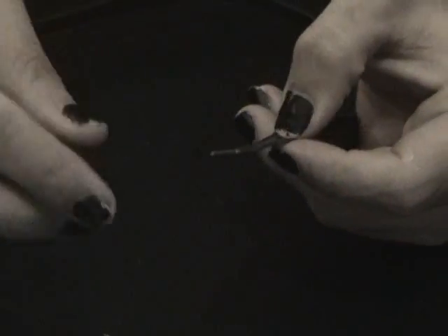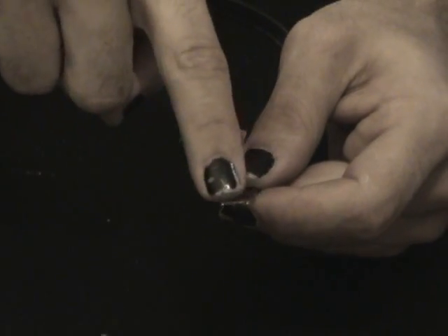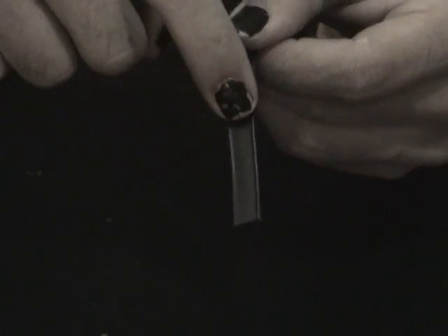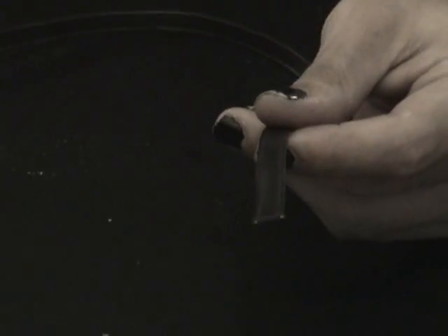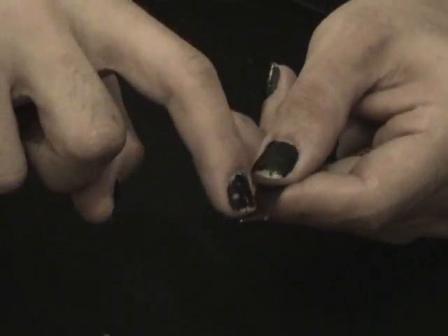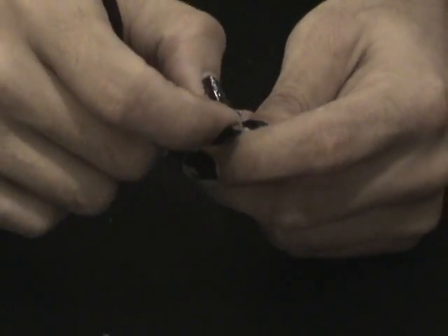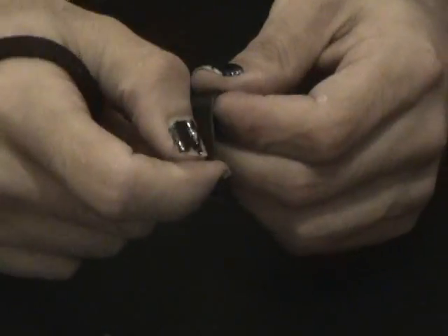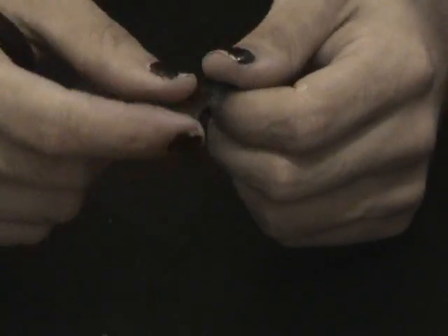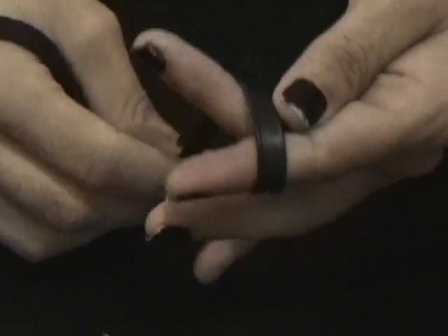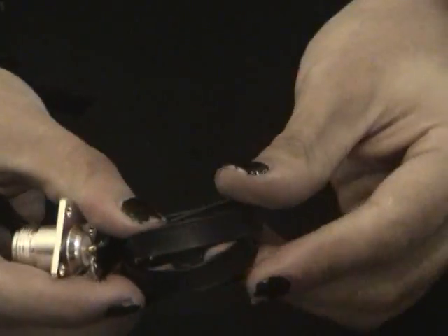To adjust the SWR, what you can do is slowly nip away at the length of the end of this until you finally tune into the frequency that you want. This will work on damn near any frequency. To hang this antenna, you put a little hole right here in the tip and you hang it by non-conductive material like nylon string or fishing line. Just don't use copper wire. And you pretty much just hang the thing up like so, it actually hangs in a straight line. And like I said, with these ladder line J-poles, they don't take up nearly as much space.